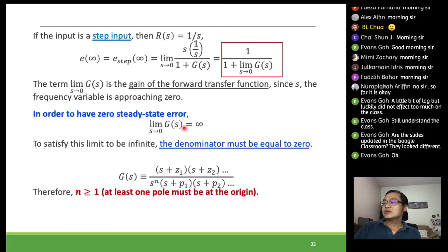Now how are we able to control this? We can always break this transfer function into multiple partial fractions, let's say in this form. So we have multiple zeros and poles and so on. There is also the case when the pole is at the origin, then we have this s, which can be of order 1 or higher.